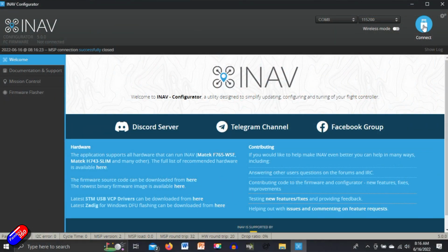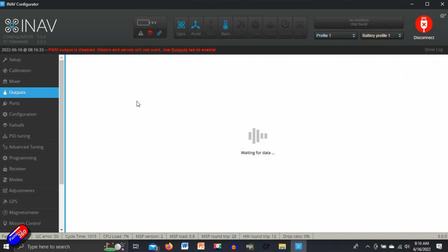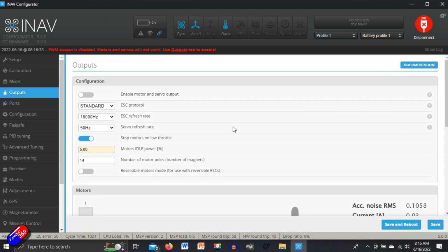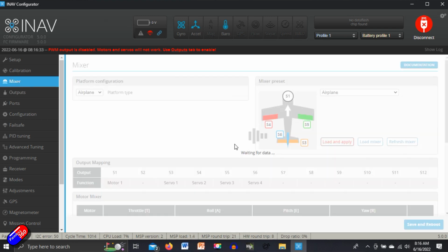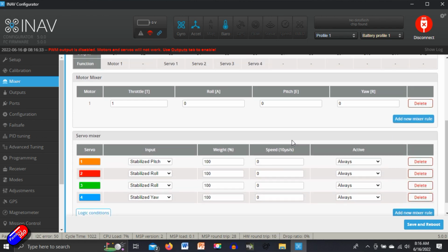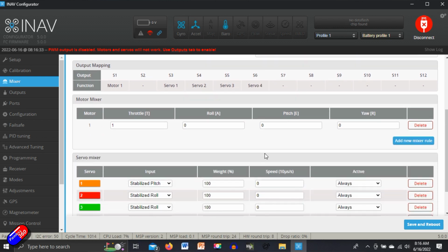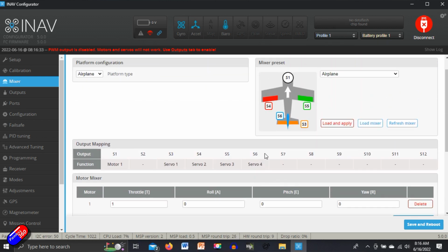Likewise, on the fixed-wing side, that whole preview image is completely changed too. When you load a new mixer, you'll see that image is completely blank, and it won't be until you load and apply a mixer that it fills anything in. That's because when you choose your mixer settings down the bottom, you have a column for servo numbers. Originally these numbers related to a table just above it, which converted them to output numbers. And above that, it used to be a static image, which just had some default output numbers, which didn't work for everything.